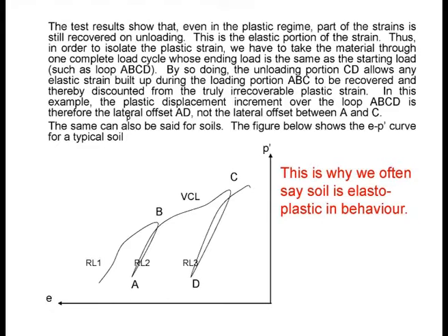You see, I have plotted the e-log-p curve. Instead of plotting e on the y-axis, I turn this thing this way. You notice that I've turned it this way. Because soil mechanicians somehow have a funny habit of plotting, whereas mechanicians plot the stress-strain curve, in this case the e-log-p curve is actually a strain-stress curve.